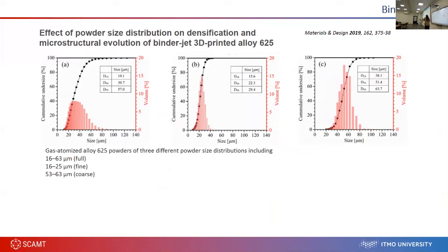That's why we can use this method for optical applications. Well, at least I didn't find any article devoted to binder jetting where we can print any structure for optical applications. I found some articles devoted to the size of powder particles, and it turned out that most of them have size more than 20 micrometers. For optical applications, it's quite bad resolution. And that's why we move on.